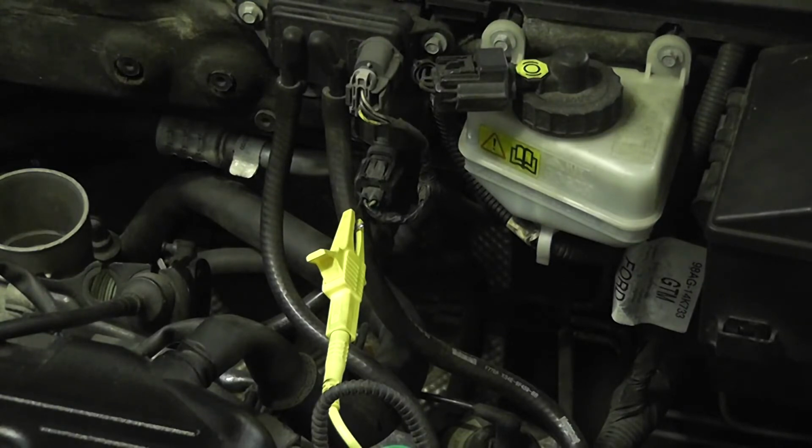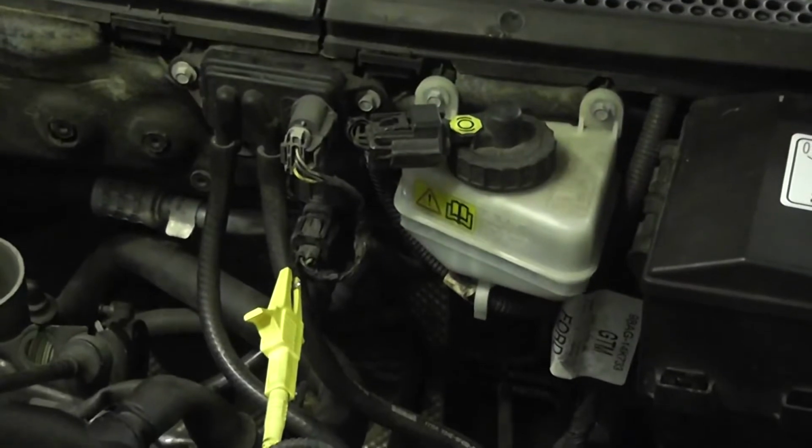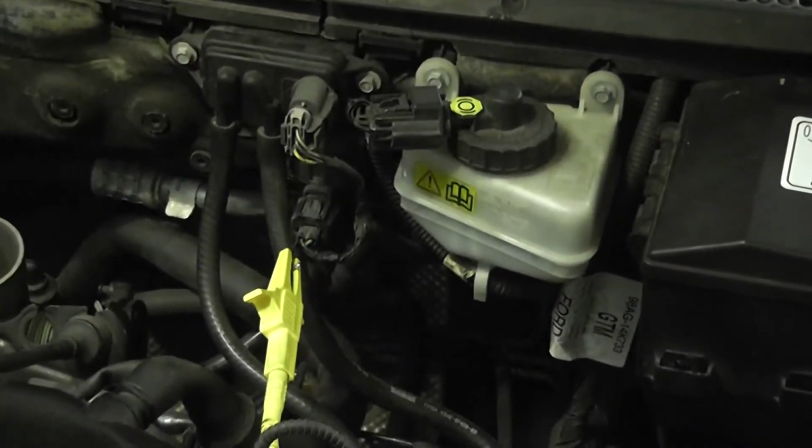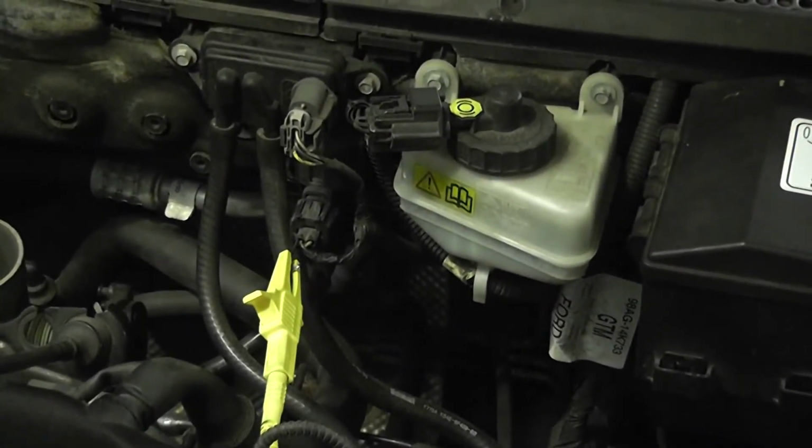Now we can confirm this test if you guys would like. Some of you like the ohm meter, so we can go ahead and do that. Next thing we'll do is we'll ohm the solenoid. What we're going to find is very, very high resistance, probably an open coil on this solenoid. We'll do the ohm check next.